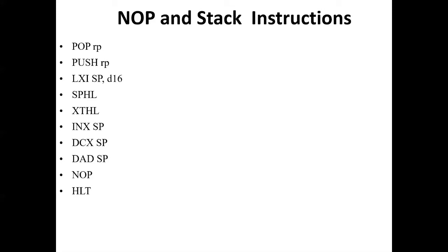Next is LXI SP D16. LXI SP D16 instruction is a special case of LXI RP D16. LXI SP instruction is used to load 16-bit immediate data to the SP. It occupies 3 bytes in memory. For example, LXI SP FC06H. So by executing this instruction, the value of SP becomes FC06H.